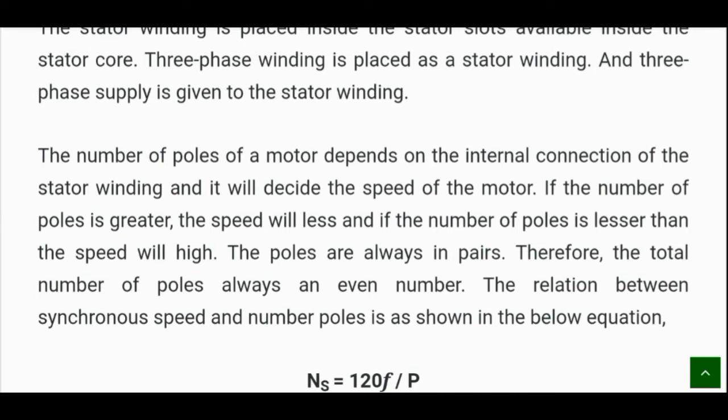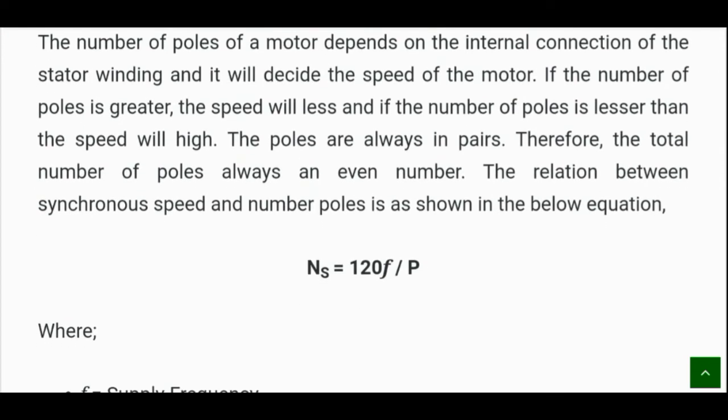If the number of poles is greater, the speed will be lower. If the number of poles is lesser, the speed will be higher. The poles are always in pairs, therefore the total number of poles is always an even number.